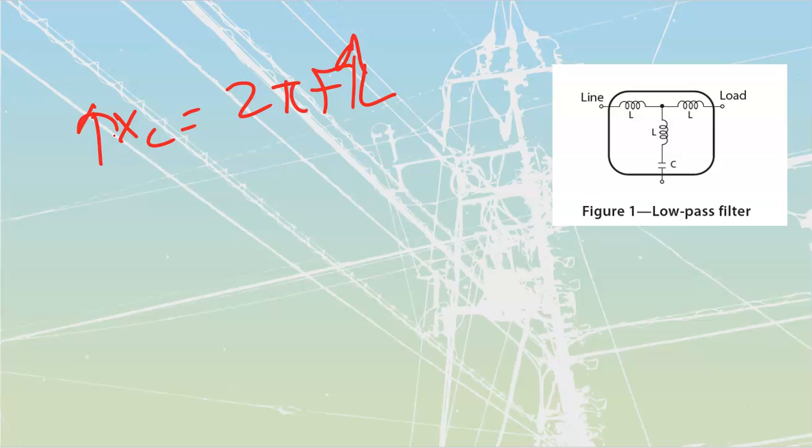But we can change that phase shift through tuned types of windings. If we do have these types of harmonic mitigating transformers, they're still going to allow the harmonics to be generated, but they're going to make sure that they don't pass all the way through these.